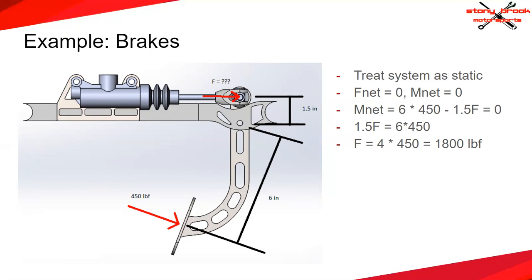For the brakes, there's actually a lot that has to go into designing the pedal. We firstly want to make sure that when we press it, it doesn't break, but we also want to make sure that the proper amount of force is being applied. This is a very brief rundown of how the brakes work. This will be talked about a bit more later, but essentially you have a pedal which presses on the master cylinder, which is up here, and there's this long tube that creates pressure in the system and sends it over to the brake calipers.